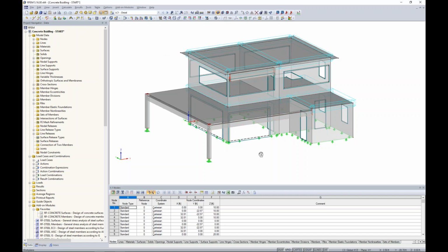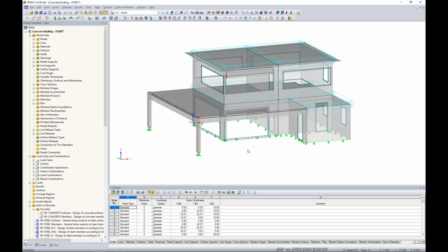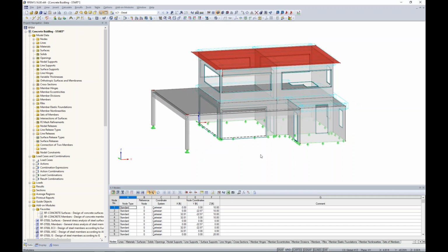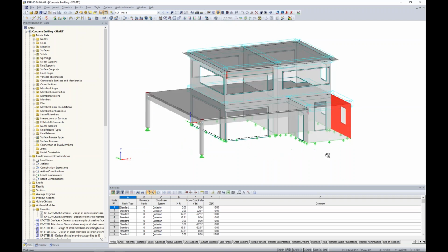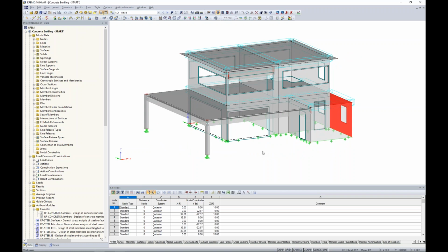And you'll notice that we do have several surface elements. So the surface elements comprise our elevated slabs at both the first level and our roof level here. Now, those same 2D surfaces are also utilized for wall elements, and you can see these in the vertical direction here. Now, surfaces do allow you to apply any type of opening within them.